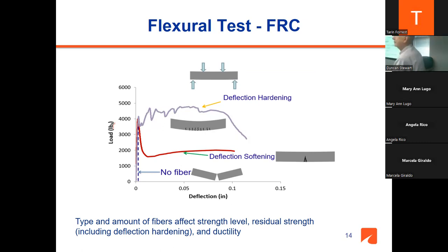So when you're mixing and you've got these fibers, they're just in the mixture, randomly? In the mix, yeah. How does that mesh with the glued? Oh, the glued fibers you are talking about? Does it have to be manually set? The glued fiber uses a water soluble glue. So when you add it into the mixer and mix, it just does a dispersion. Because if you put in loose fibers, they tangle, and it's very difficult to separate them. But glued fibers appear to be well dispersed in the system, separate from each other because of it. Very good. Thank you so much.